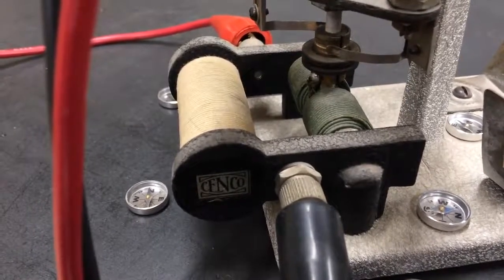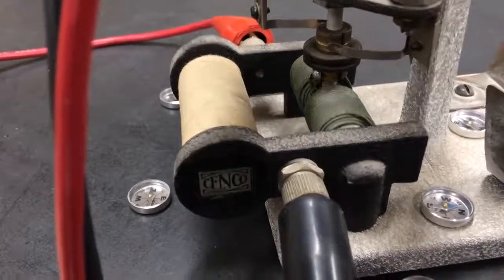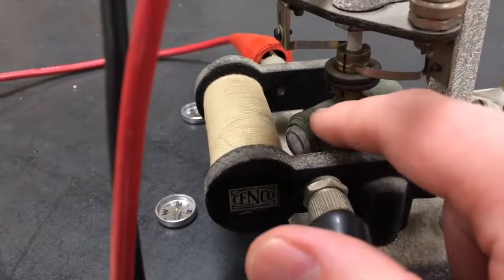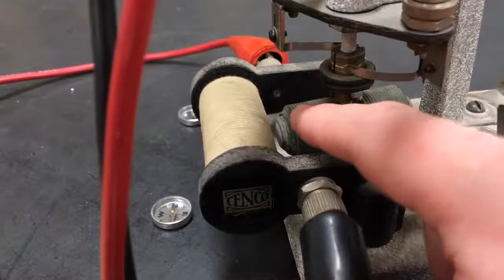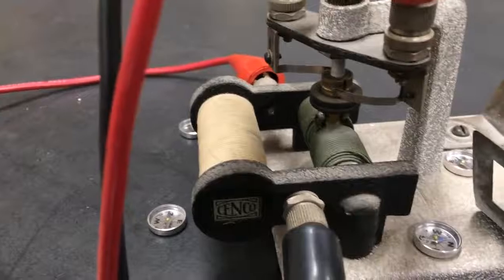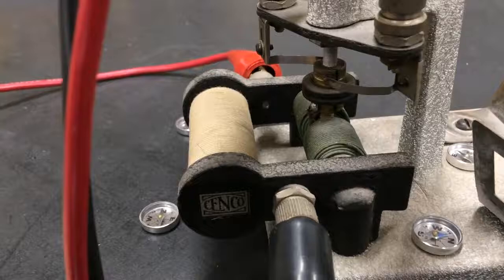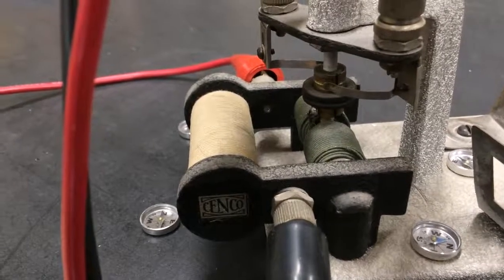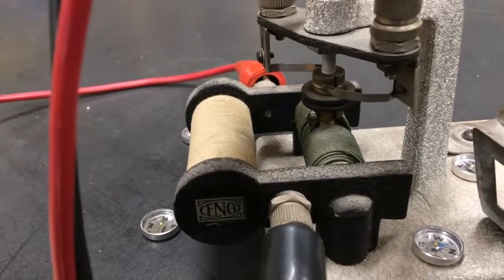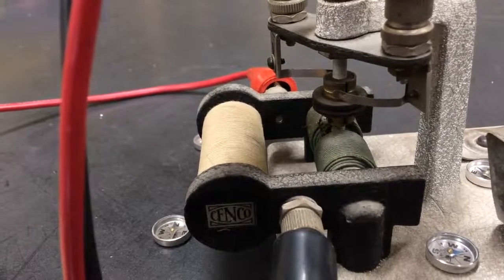So that's going to pull the coil towards the left. And because of the way it's wired, the other side is actually going to be pushed away. Well, that's great until it turns 90 degrees. Then the opposite arguments are going to apply, and it's going to get pushed back the other way. And it wouldn't go anywhere. It would just get pushed back and forth. So in the simpler motor you saw, the one from SciToys, we solved this problem by just having the motor be off half the time. The rotating part only made contact with its power supply 50% of the time because I only scratched off the insulation on half the wire.